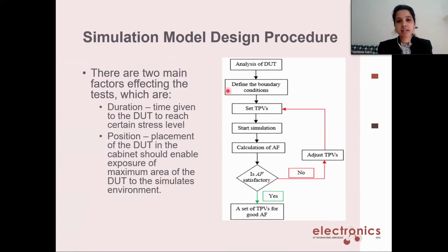So nowadays, the test parameters are set for a particular system based on experience and from standards and guidelines which were developed a few decades ago. And each component is very different from another on the basis of the structure, materials used, and the dynamics and complexities of the component. So the test parameters for this accelerated test have to be altered for the particular component.